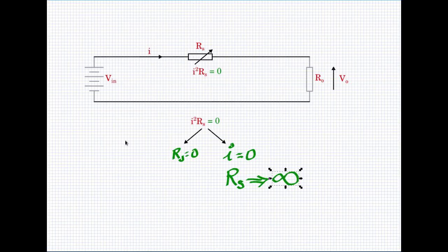So what does this mean? It means that when the switch is a short circuit, the voltage across the switch is 0, so there is no power dissipation. When I is equal to 0, the switch is an open circuit. So when you make the switch open circuit, the current through it is 0, and then also the power dissipation across the switch is 0.